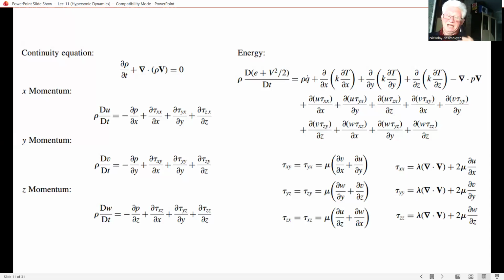Just as in the case of the Euler equations, there is no general analytic solution to the complete Navier-Stokes equations. However, in analogy with the approximate solution of the Euler equations, we can simplify the Navier-Stokes equations via an appropriate set of assumptions and obtain approximate viscous flow results.